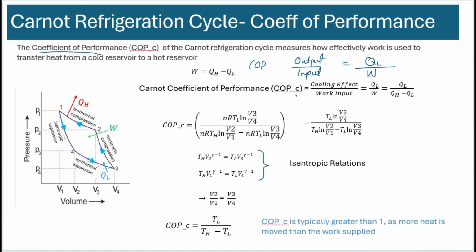Whenever it's a refrigeration cycle, we don't call it efficiency, we call it COP. You will also hear EER later on, but I'm not discussing it right now. It's the same as COP, but in different units. So think of COP whenever you're discussing efficiency of a cooling system.